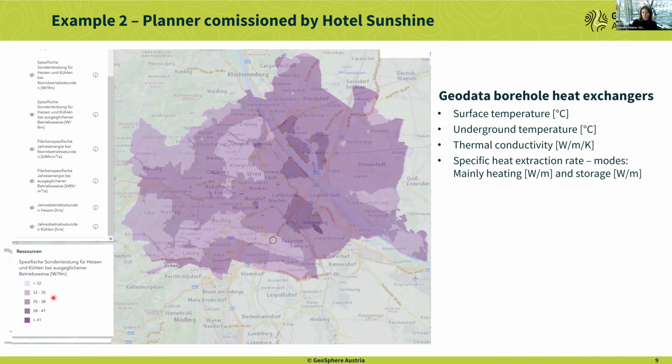And then it gets a little bit complicated because as of now, we only had geological data. But if you also want to know the energy and power of the borehole heat exchangers, you also have to take into consideration the operation and the configuration of the boreholes themselves, because the heat extraction rate strongly depends on the depth of the boreholes, on the distance between the boreholes, on the operation mode, the operating hours. And so if you want to calculate this heat extraction rate, you have to fix those operating parameters. And that's what we did.